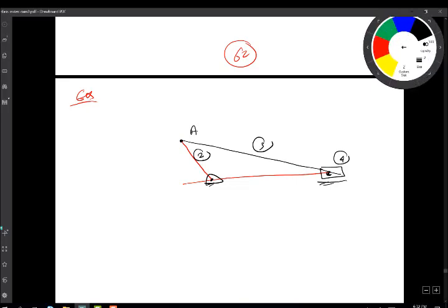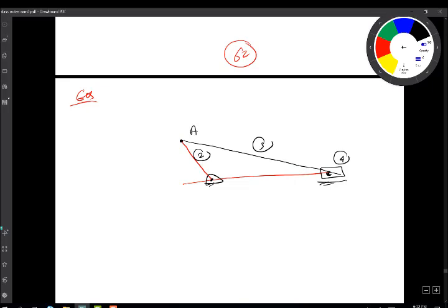And there are the ones that are easy to find, the quick ones, such as 1, 2 here, because this is common between 1 and 2, correct? And this one is also easy to find because it's common between 2 and 3. So I put 2, 3 on it. And the other pivot, every pivot is very easy. When I see a pivot, I know there is a common velocity at the pivot. This pivot here links link number 3 and link number 4 together.